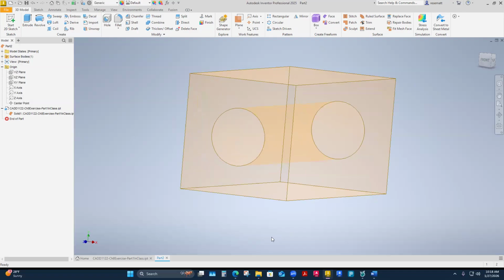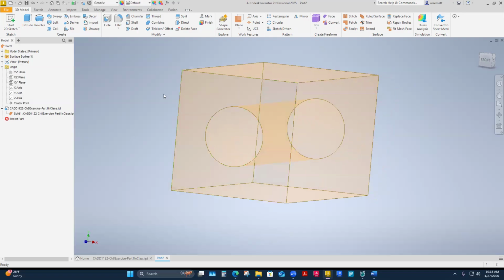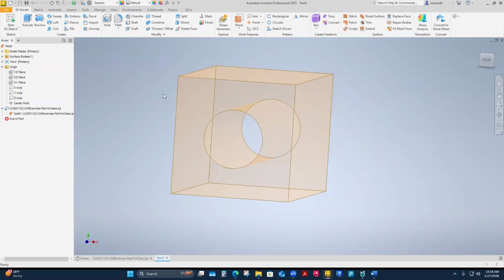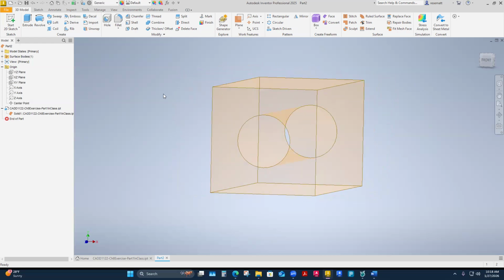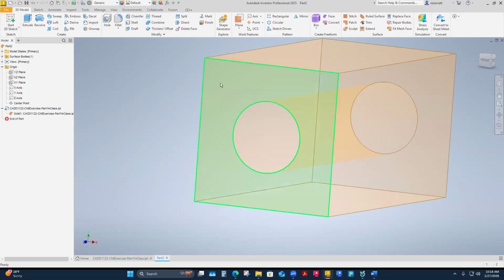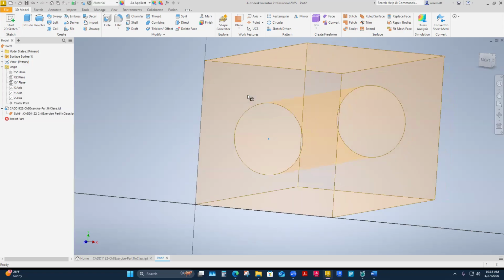Now I can use this like I would do a sketch on another object. As you build out your normal parts, you do a sketch, build a feature, then you might add a hole, so you select a surface and add a sketch, and I can work from it the same way now. I can design this pin and I don't have to think of it as a standalone part. I can draw a pin that fits in this hole from this surface. So I can select this surface, new sketch.